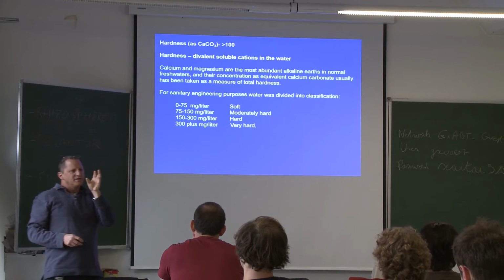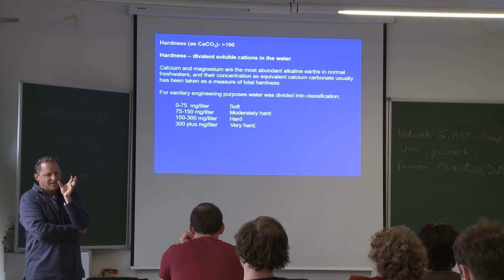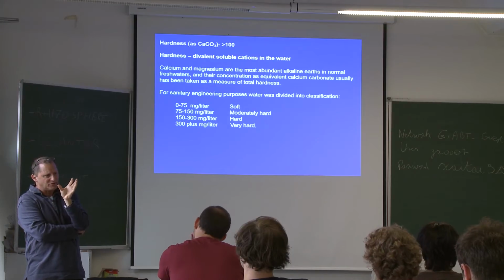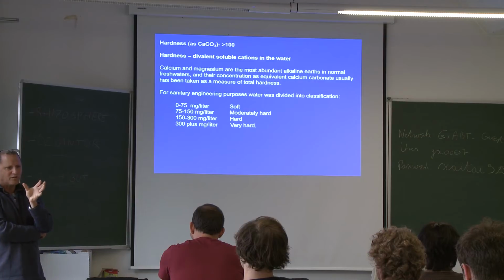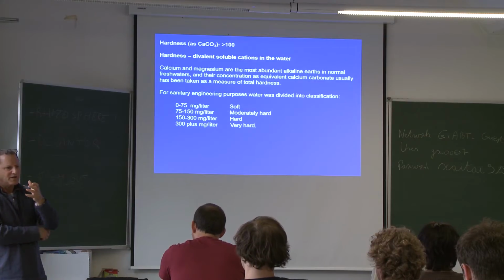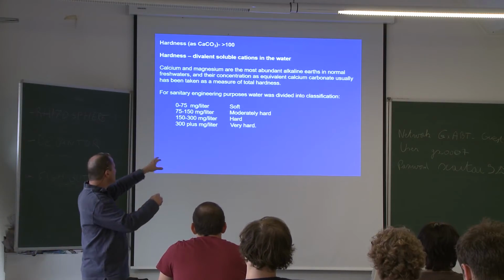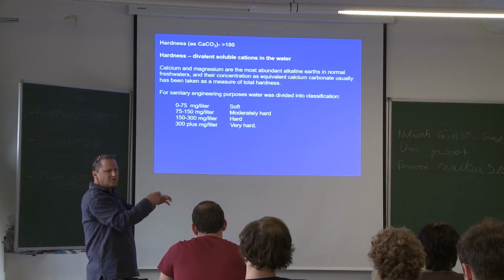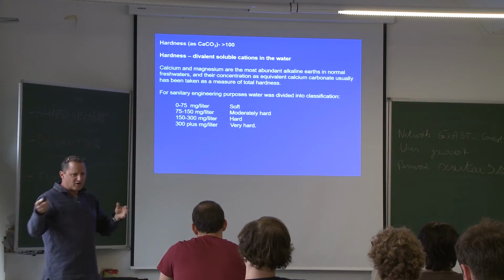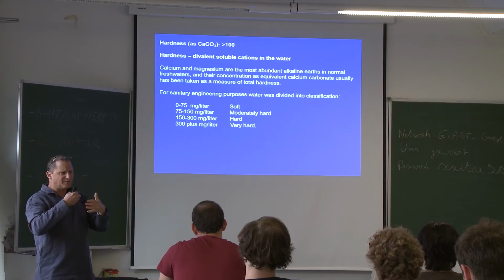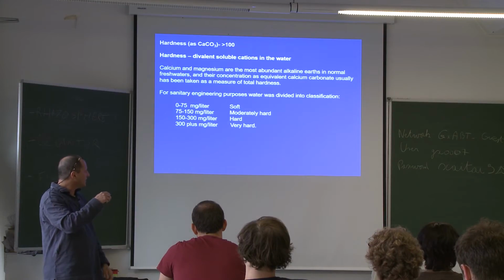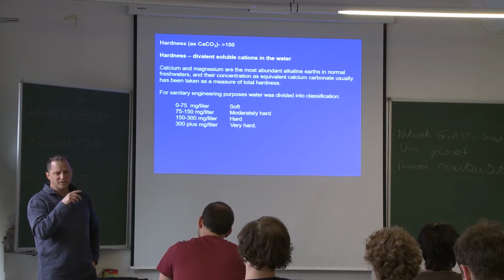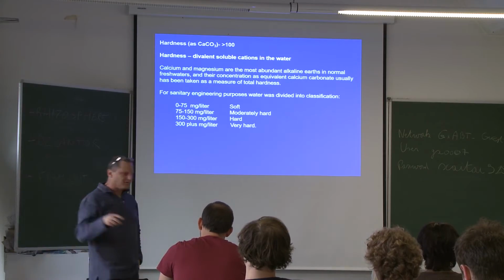Because often alkalinity, which is a very important measure, is contributed by calcium carbonate from limestone. And then there is a correlation between the amount of calcium and the amount of calcium carbonate. Okay? So it sometimes overlaps, not always. And it's not only calcium carbonate, it's sometimes dolomite, which is calcium magnesium carbonate. Okay?